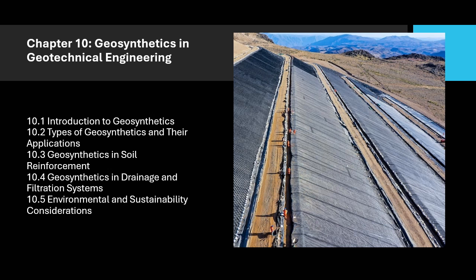3. Wastewater treatment plants. Geomembranes are used in various applications within wastewater treatment plants to line holding tanks or ponds to prevent the leakage of contaminated water. 4. Containment of chemicals or leachates. They are used to prevent hazardous chemicals from leaking into the environment in industrial sites or hazardous waste facilities.